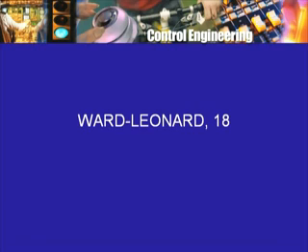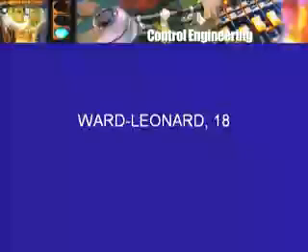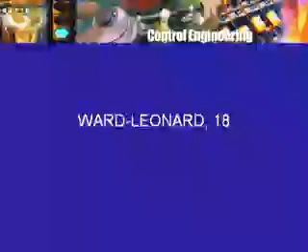Of course, as I mentioned earlier, in a locomotive application such as in the Mumbai suburban system, the configuration preferred is not shunt or separately excited motor, but series connected DC motor. But in some applications you may prefer the separately excited DC motor, and therefore a person with a hyphenated name, just one single person by name Ward Leonard, an American engineer, introduced this idea, which looked, and even today will look, a little not only complicated but involving too much of equipment, but it solved the problem.